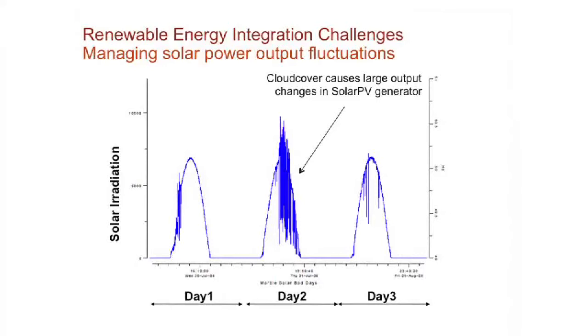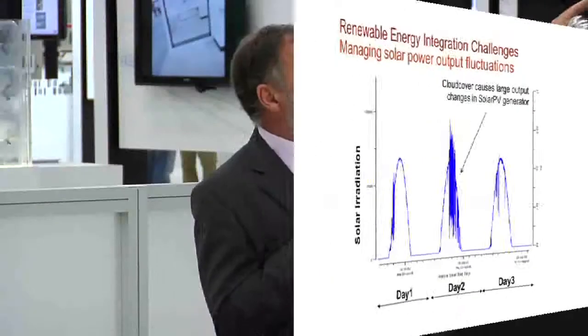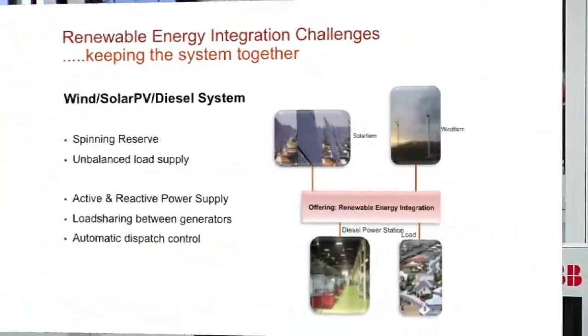So a flat plate collector out there on a cloudy day will get bounced back from the clouds and actually produce more than its rated capacity. And, of course, you can actually see the clouds come across and drop the incident radiation down. The concentrating collectors like the Greenvolt ones around the back here don't see the over-generation because they're particularly focused on incident radiation, but they will absolutely see the loss of generation on a cloudy day. So the solar boys that seem to criticise the wind boys can't get out of the problem, okay?